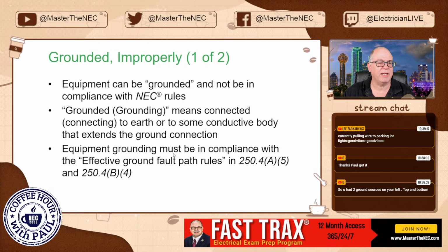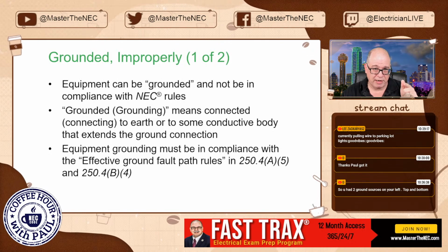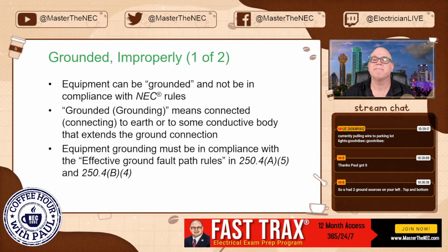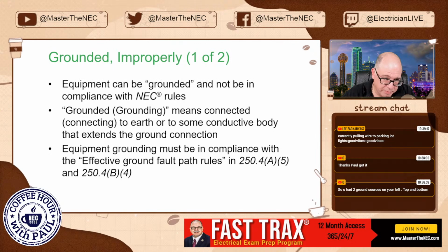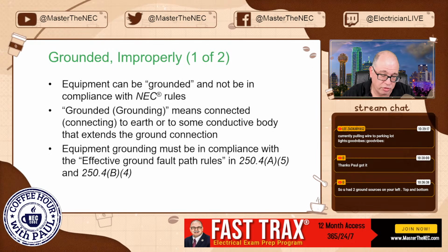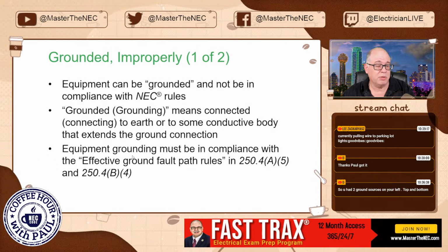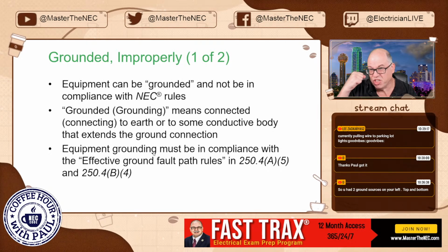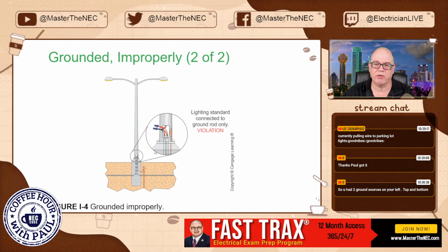Lee's doing some parking lot lighting. Remember, Lee, make sure they always run an equipment grounding conductor out there, okay? Now, I hate to say this, it doesn't always have to be of the wire type. It could be the type of wiring method you're using in 250.118, but I'm a wire guy, so most people want to put that wire in there. They just feel good about it. All right, so here's the example we saw right here.